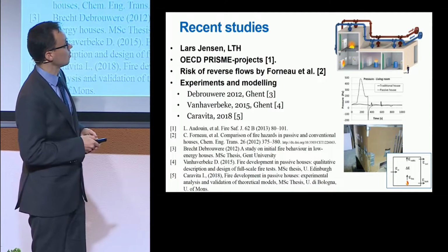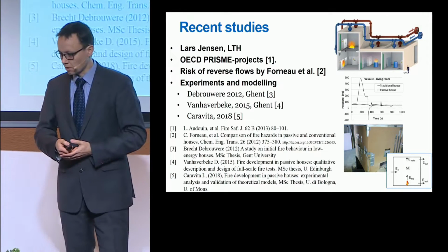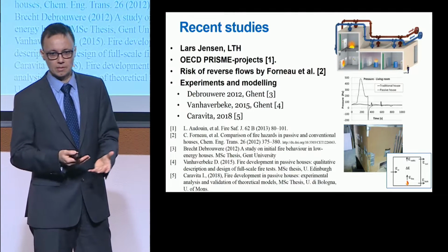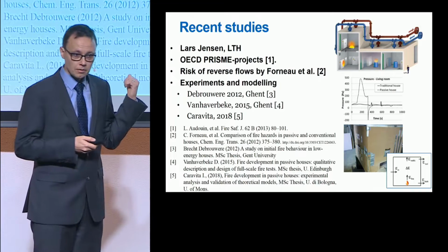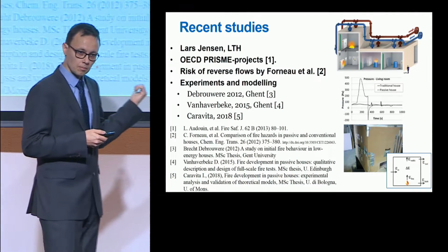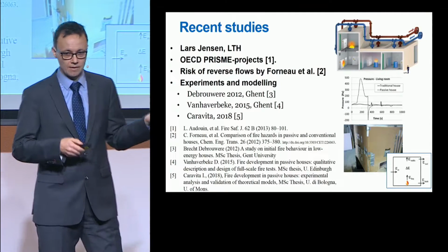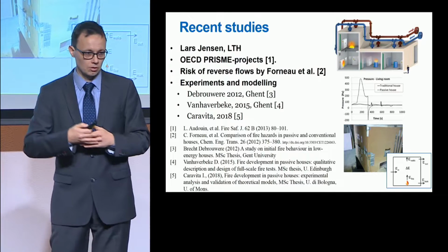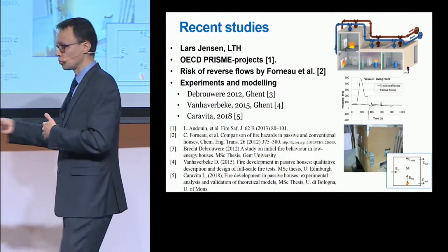They have a facility called DIVA, which represents a nuclear facility with very airtight containment, and there we have measured peak overpressures of several thousand Pascal. We have observed how the pressures can change the ventilation arrangement entirely. It can reverse the flows.